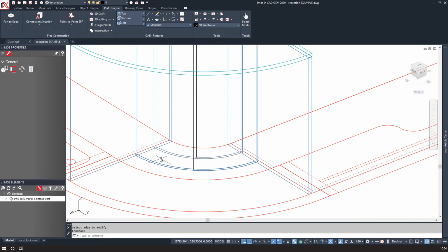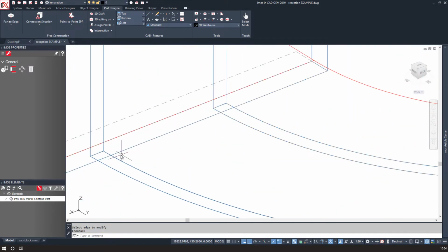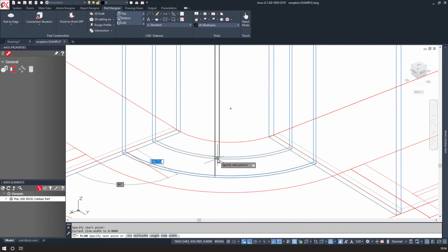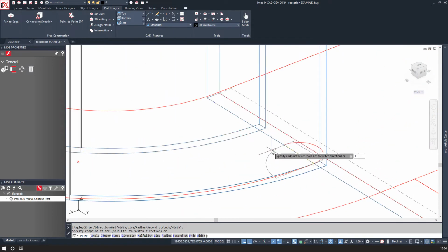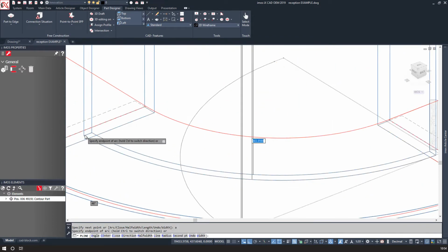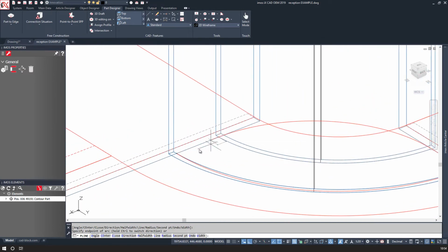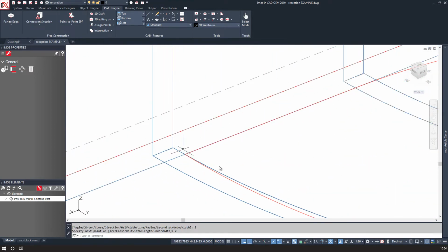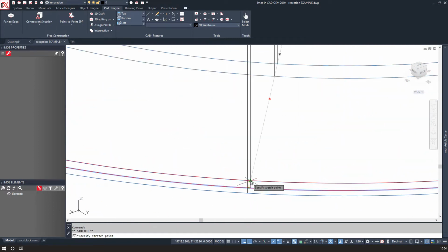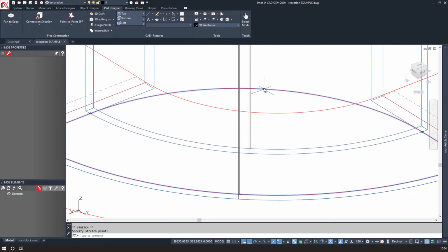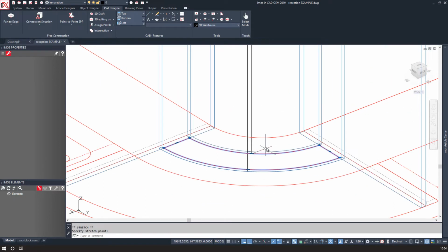So I'm going to need some sort of vertical support for these pieces running up and down. So again, I'll use the contour part tool, and I need to use the polyline from AutoCAD to draw my internal rib or support or whatever you may call it. So select this geometry and I'll just snap it to the inside piece. And then I'll move it up so it's not completely on the floor.